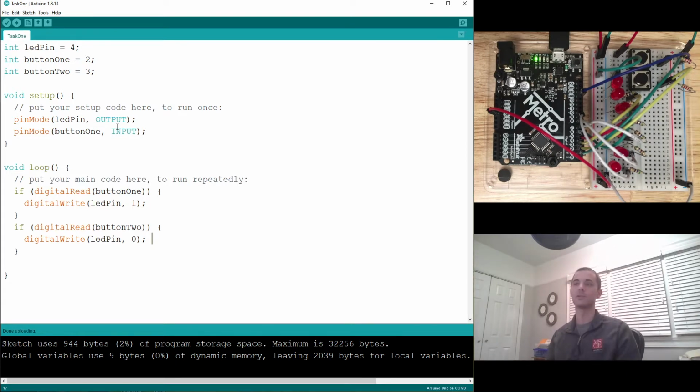And so the amount of time, let's say, gosh, I forget how many cycles it takes to do an analog or digital read. I think it's 4, and it's running at 16 megahertz. So in theory, I think if you do it efficiently, you can read an input pin on the order of megahertz. We're not doing it as efficiently as possible, even though this is very simple.